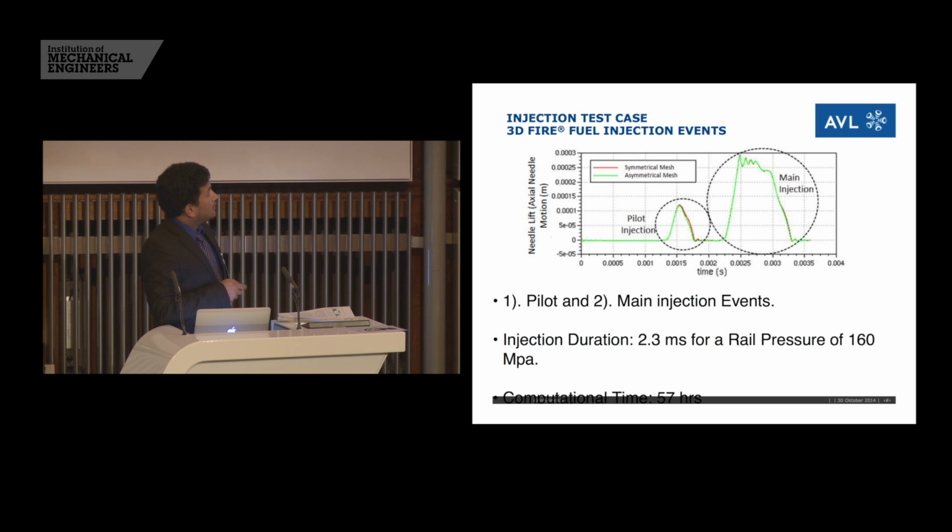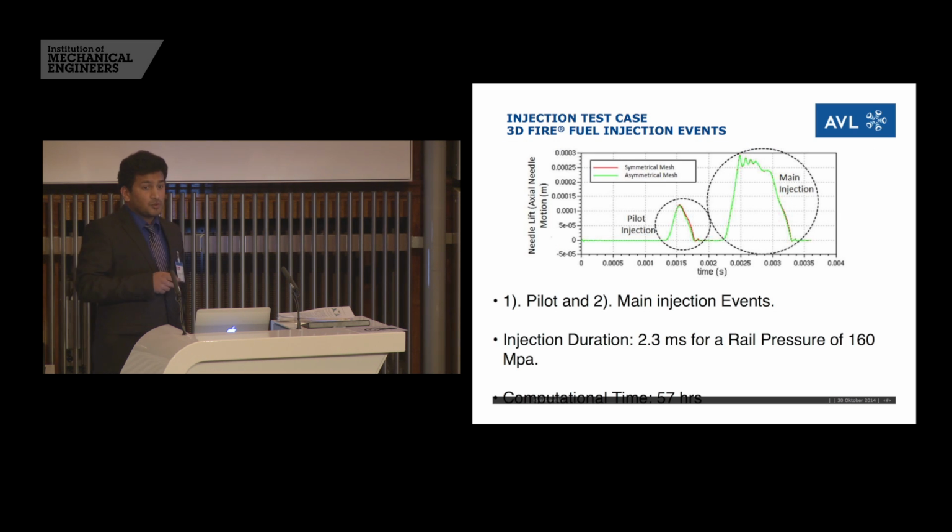And for the injection events, I consider here there are two injection events. One is the pilot injection event, and the second is the main injection event. The maximum lift for the pilot injection is around 130 micrometer, while that for the main injection is around 300 micrometer. I know this is a bit small compared to the normal conventional injectors, but we consider this